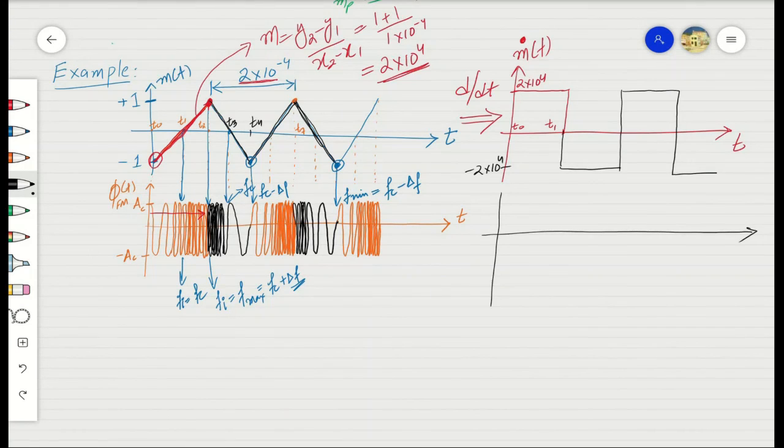We have obtained the derivative signal of the information signal. With respect to this derivative signal, if the frequencies of the carrier signal are modified, we can generate a phase modulated signal. So for this span, we have a high constant amplitude. Since the amplitude is constant and high, a high, constant frequency will be generated. So for the positive peak of the derivative of the information signal, the maximum frequency of the modulated signal